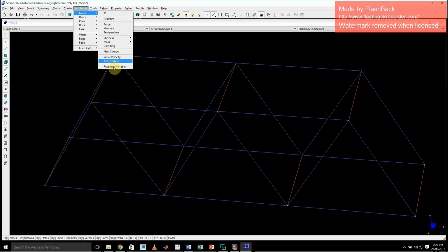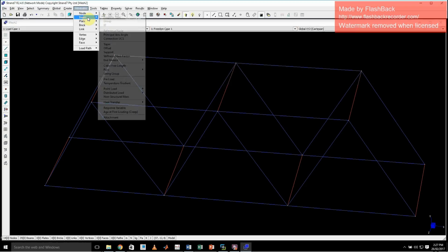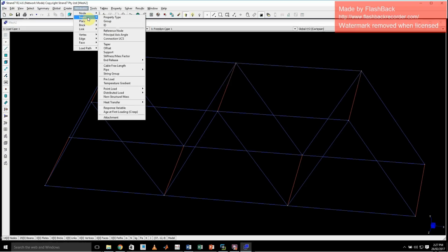You can apply things to more than just nodes. You can apply properties to beams. So if you have a distributed load, which was mentioned in the notes on structures, so a force that goes uniformly distributed across a beam, you can come and apply that to a beam using either a force principle or a force global, and put those types of forces in here.